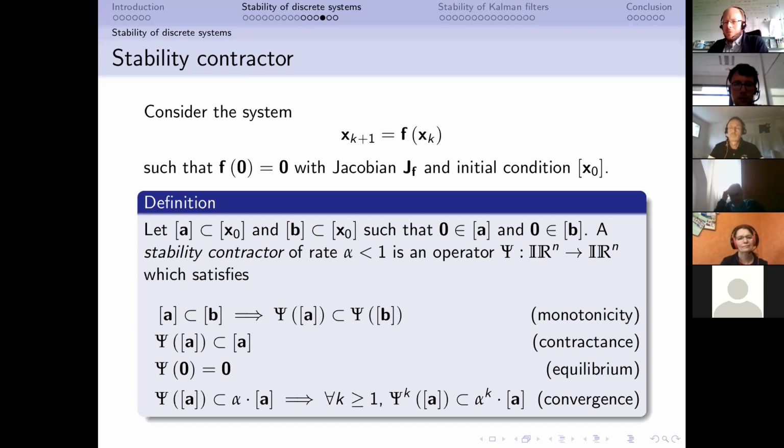If your system model is nonlinear, you don't have any a priori bounds on how many successive evaluations of the state equations you need in order to show observability. For a linear system model, it's obvious. It's just the number of states. That was something proven by Kalman. But for a nonlinear discrete time system model, in general, there's no upper bound. And that's something that you can even see in this framework.